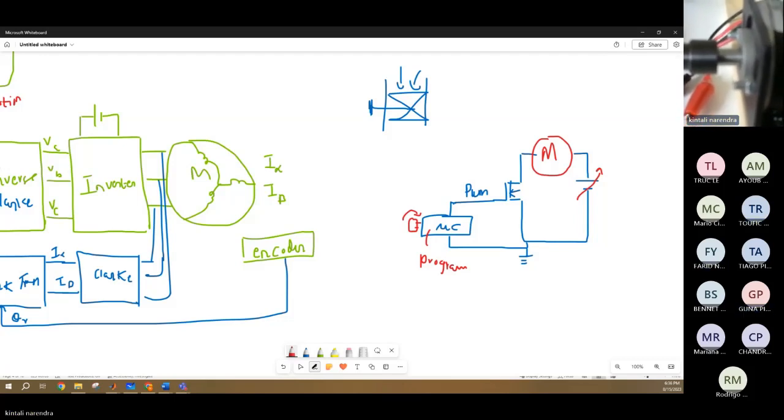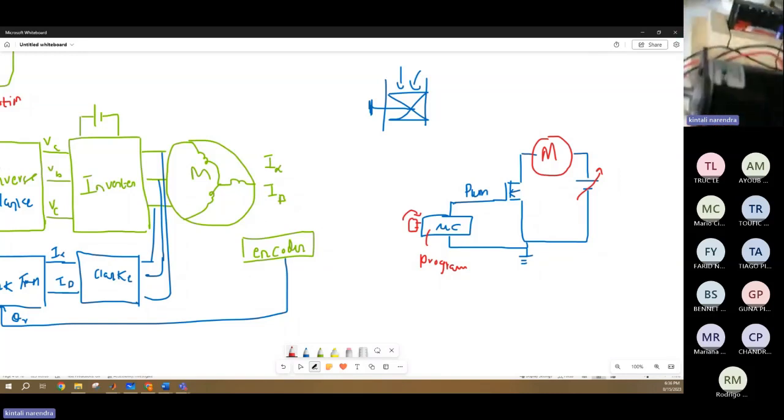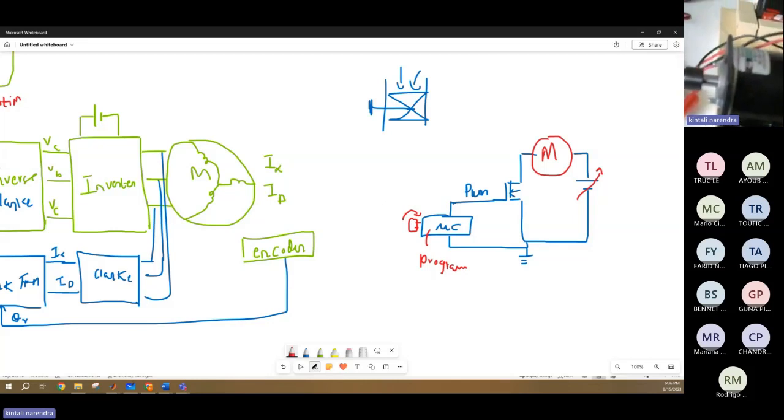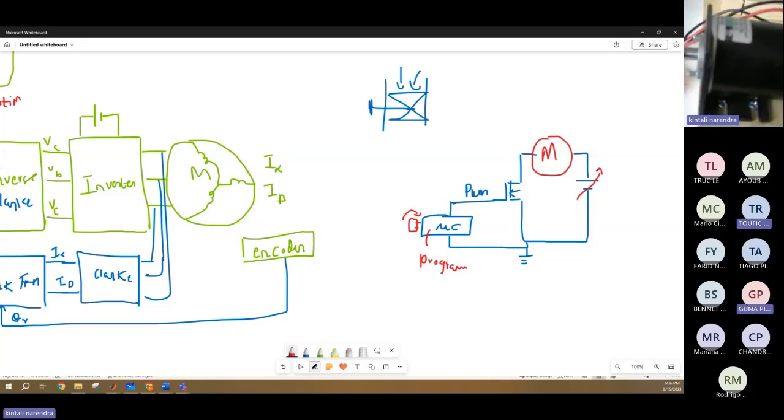Not a complicated experiment, but here I want to show how, with a small knob, even though this motor is only a 12 volts motor, a 240 volts motor also you can control by using this technique. All you need to do is find the right MOSFET. That's it.